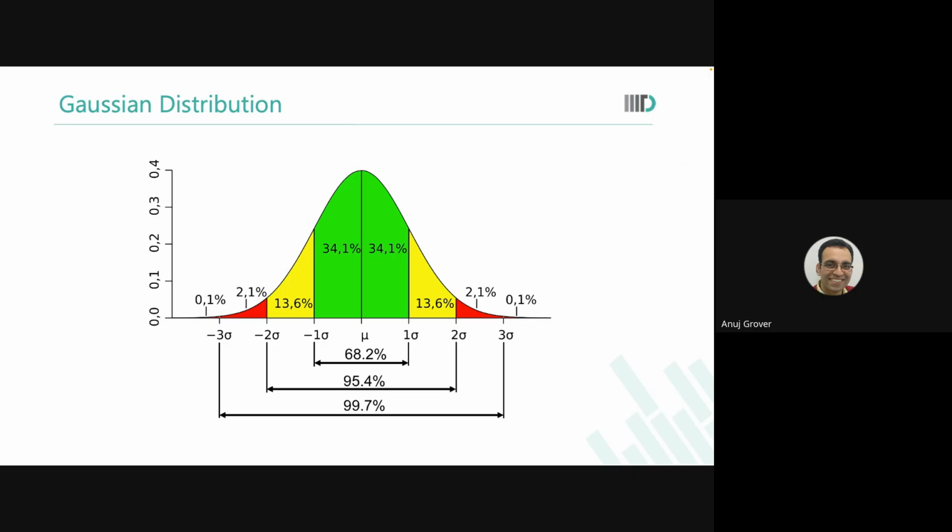You think for an enterprise server or a high performance design, you will need to go beyond plus minus 6 sigma. Not 6 sigma qualification, it is 12 sigma. In fact, I'm saying 13 sigma or 14 sigma may be required depending on what is the on-chip capacity that you're talking about.